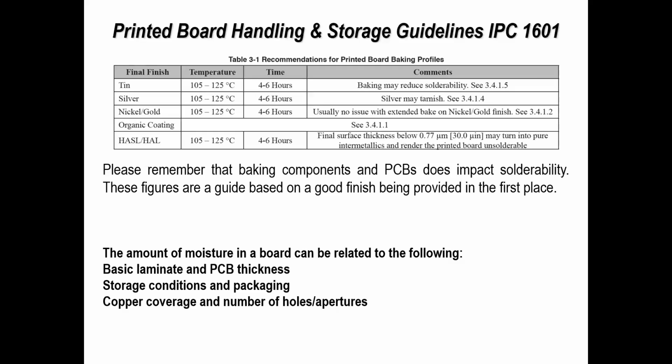So let's just talk about the boards again. There is an IPC standard dedicated to printed circuit board handling and storage, which also talks about baking. And if you look in that standard, there are recommendations for bake times and bake temperatures. Now, if you've got moisture in a board, you will always have to bake above 100 degrees C. You don't want too high a temperature, and you don't want too long a time at baking, because every time you heat up and cool down a board or a component, it has a very small effect on the wettability and solderability of that part. So at some point, you get to a situation where you are causing yourself a solderability problem, and it's more of a problem with certain finishes than others, and that's true also of components.